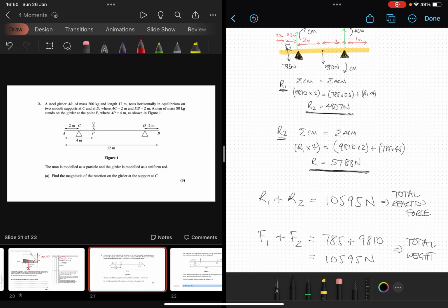Thirdly and finally, here is your two pivot kind of question. Okay, so that would be really good for you to have a go at one of these as well. The thing to notice in here, though, and this is the other way that examiners sometimes throw us, is they haven't given you weight or force. They're giving you mass. So you would expect to be multiplying that by 9.81 to turn it into force, and you'd be expected to do likewise with that.